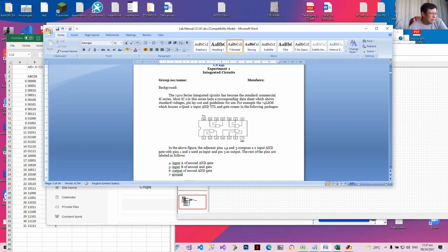Okay, you can watch this in the video, which is in the topmost part of our class. And you number the pins. You start numbering from the lower row, from the left to the right. Which means you number 1, 2, 3, 4, 5, 6, 7. And then you continue by going back up, but this time you start from the right. So 8, 9, 10, 11, 12, 13, 14, the opposite way.